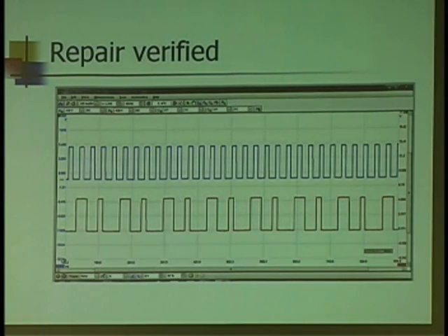It also depends on where, if you're doing a voltage drop test, where are you referencing your measuring tool, right? What if I hook my multimeter or my scope to the ECM ground? Would I get now a voltage drop that should be closer to the 0.1 or 0.05, the normal of what I would expect to see?